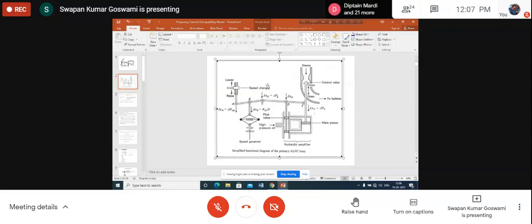C moving up means this point is also fixed, because there was no oil movement. Unless there is any oil movement, you cannot change this position. But you have given a push here, so as a result, C will be moved up. As C is moving up, along with C, D will also be moving up somewhat.